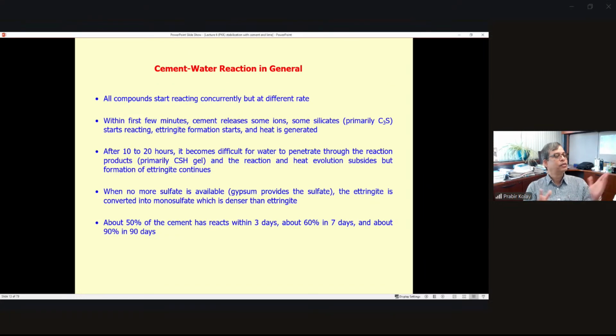So as I mentioned, there are different components of the cement, and then how it reacts with water. Now when you add it to the soil, you need to see the chemical composition of the soil itself. Soil is mostly silica and alumina, correct? Silica, alumina, iron, there are three things. And then also how the chemical reaction takes place when you add these chemicals. Finally, it is going to form calcium silicate hydrate, calcium aluminate hydrate, or calcium silicate aluminate hydrate, or maybe ettringite, or maybe calcium monosulfoaluminate.